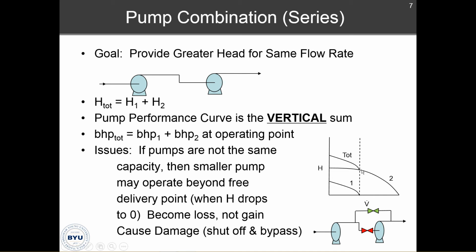And once that's done, then that system curve for the pumps drops just down to pump 2. What does this mean? Well, this is one of the challenges of operating in series. The benefit is that you can indeed have a higher head with the same flow rate. So if your system curve looks something like this, then you would be able to operate much higher if you have the two pumps together.